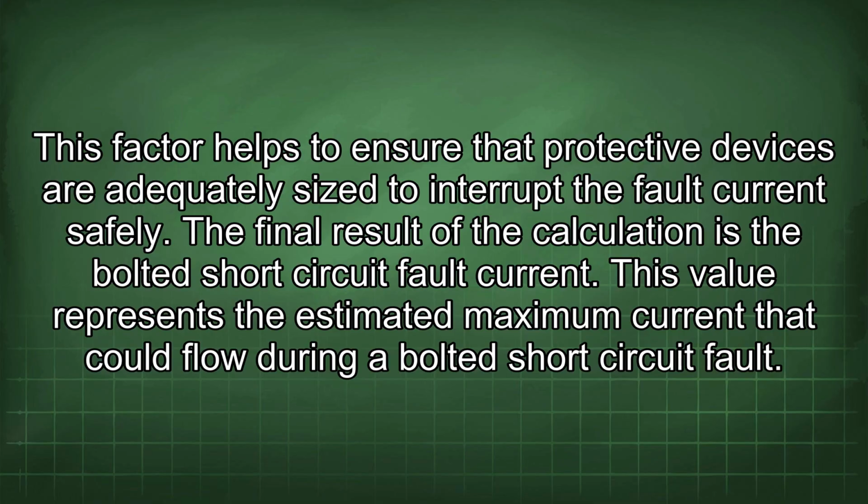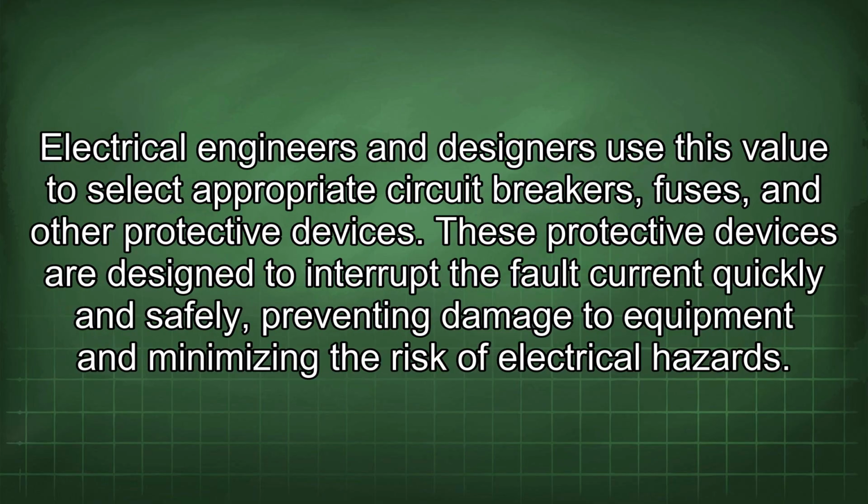The final result of the calculation is the bolted short circuit fault current. This value represents the estimated maximum current that could flow during a bolted short circuit fault. Electrical engineers and designers use this value to select appropriate circuit breakers, fuses, and other protective devices. These protective devices are designed to interrupt the fault current quickly and safely, preventing damage to equipment and minimizing the risk of electrical hazards.